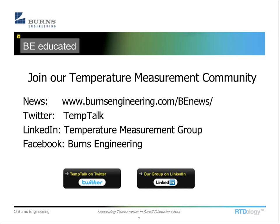I mentioned that example of measuring room air temperature, and we typically need a little more immersion length and to be a little more cautious about minimizing the stem conduction issue. Again, a very tip-sensitive thermocouple could be the best technology to use.